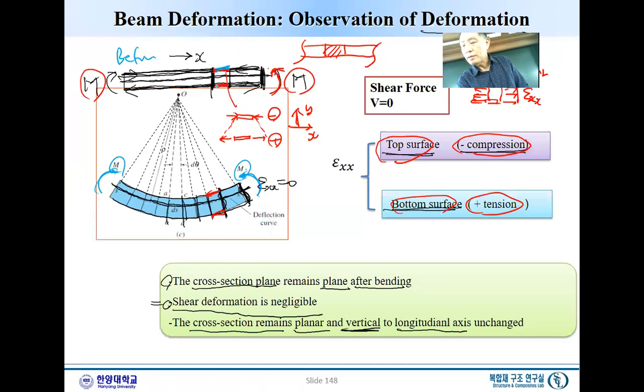Now, what we can clearly say is, let's take a look at the upper one. Upper skin, just a little portion of the upper skin and lower skin. Look at this guy, and what's happening here? This length or whole line, is it extended or contracted? Yes, it has certainly contracted. In terms of strain, it's negative, compressed. Am I right? That you can easily guess.